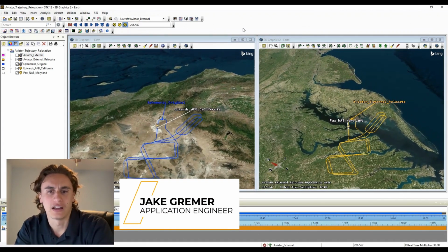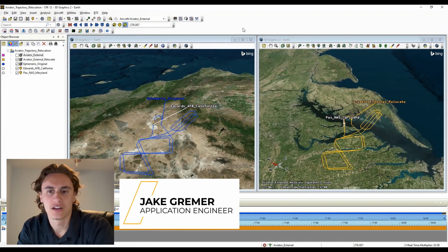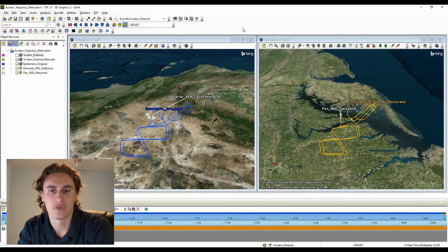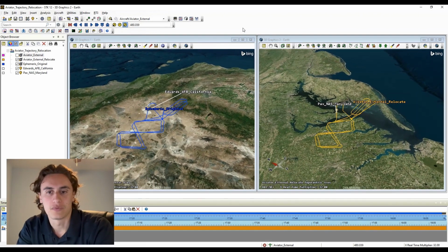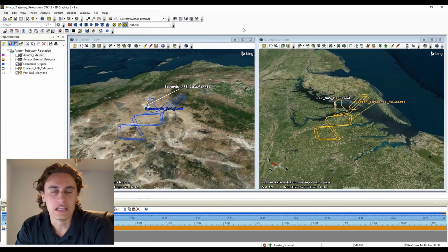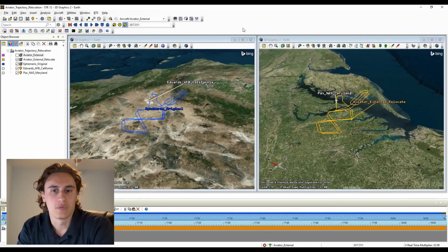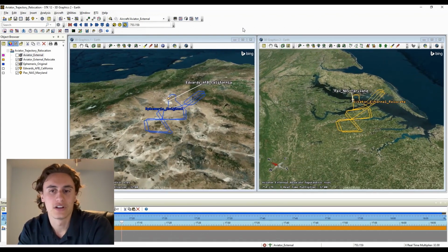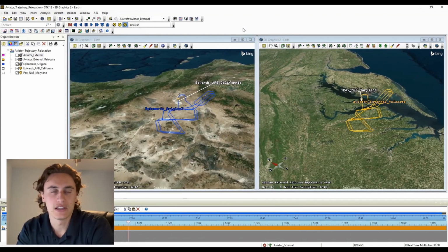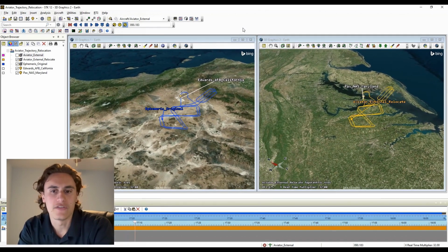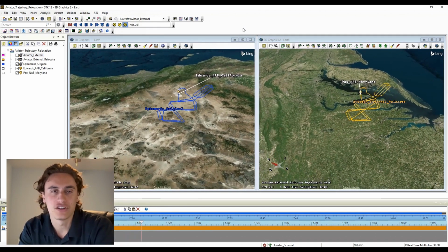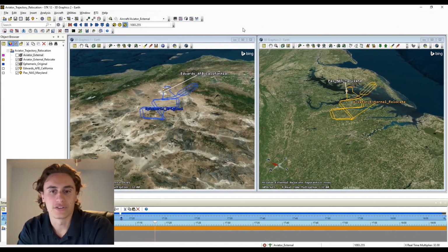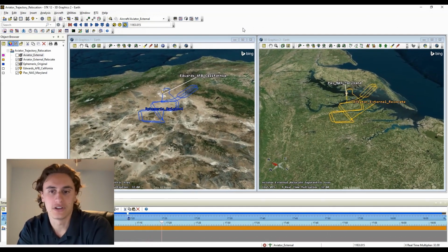In this video, I'm going to be highlighting for you the enhancements we've made to using external ephemeris files in STK Aviator 12.9, releasing with 2024 R2. In 2023 R1 or STK 12.6, Aviator added the ability to use external ephemeris files or captured trajectories to create Aviator objects, allowing Aviator to determine the appropriate attitude, aerodynamics, propulsion, and thermal models for those external ephemeris trajectories.